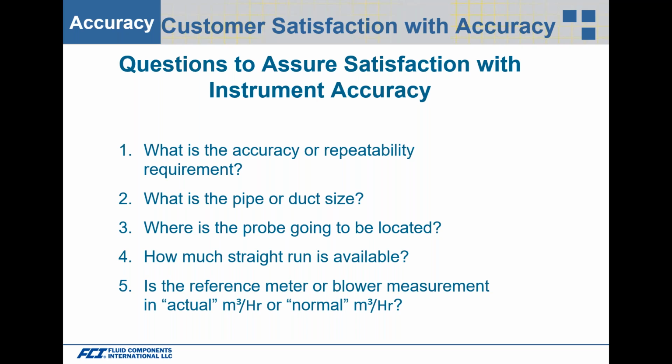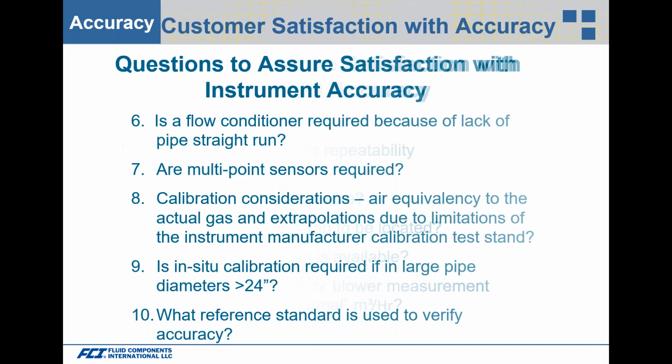And as you know, gas is compressible. It is affected by temperature and pressure. So it's very important that we're not comparing mass to an actual blower curve. And then, is a flow conditioner required because of lack of pipe straight run?